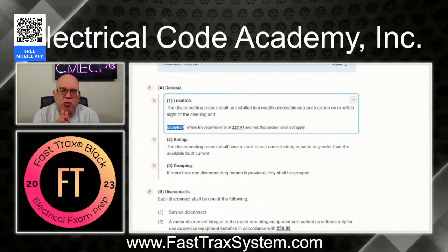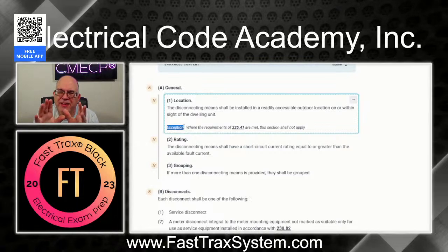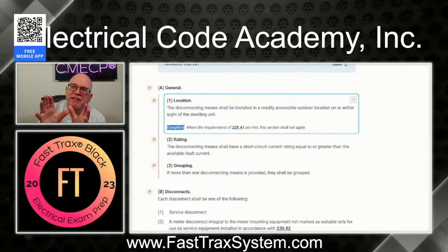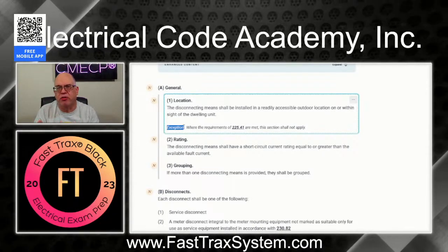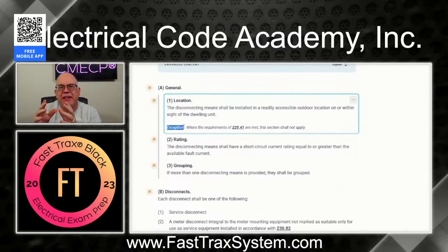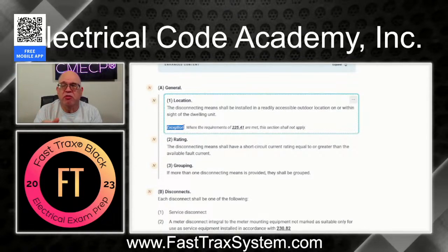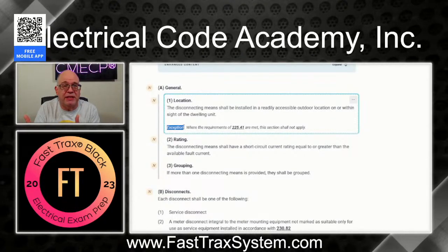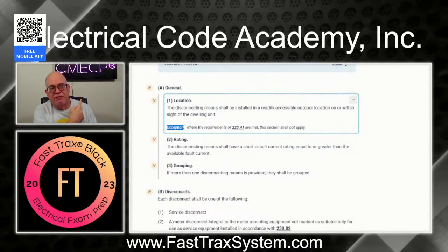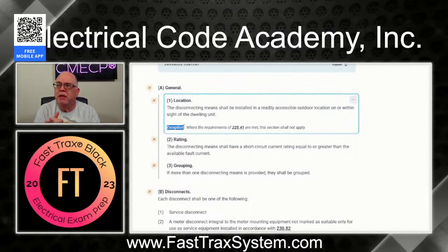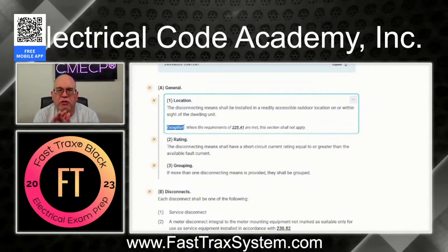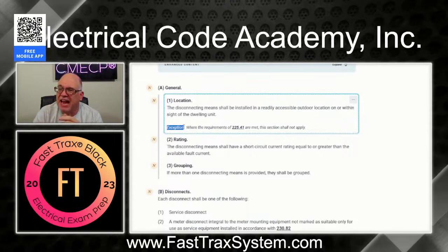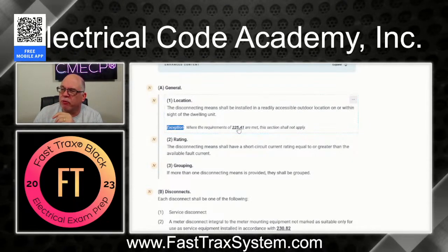Well, in the 2020 code, if you did that and you took the feeder to the structure or the building, then the emergency disconnect would not be at the building. So if a first responder came, they absolutely wouldn't know, possibly they wouldn't see anything. So they'd have to go hunting for where this would be. And so in the 2023 edition, they added 225.41.